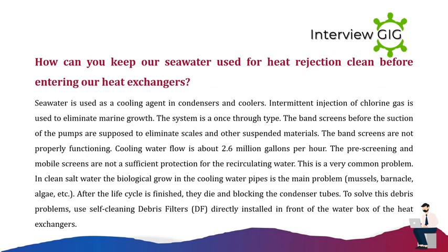Seawater is used as a cooling agent in condensers and coolers. Intermittent injection of chlorine gas is used to eliminate marine growth. The system is a once-through type. The band screens before the suction of the pumps are supposed to eliminate scales and other suspended materials. The band screens are not properly functioning.